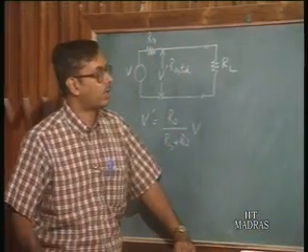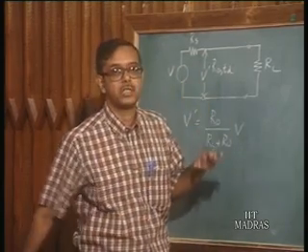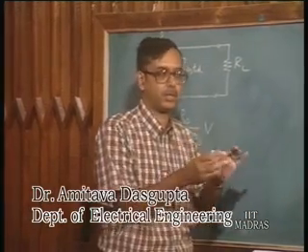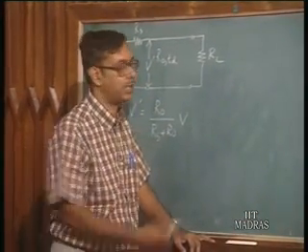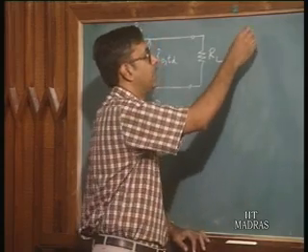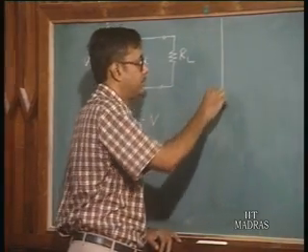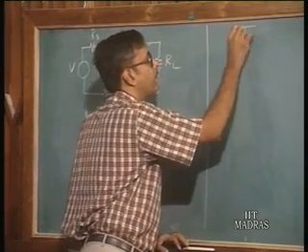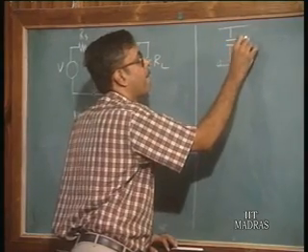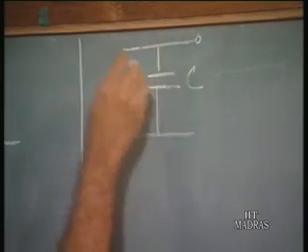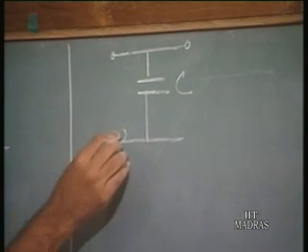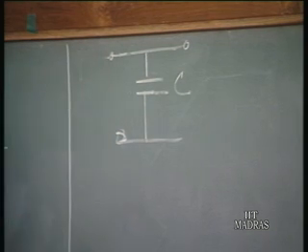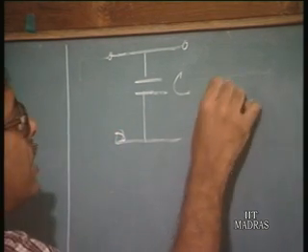Now we shall look at the different models which are used to represent the transmission lines, and which is the best model to use for a particular situation in order to simulate the transmission line. Suppose we replace the transmission line by just an equivalent capacitance, say C, and of course you have the source resistance from the voltage source. This model is called the C model.